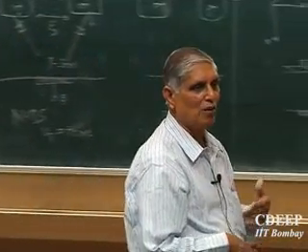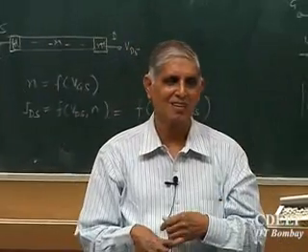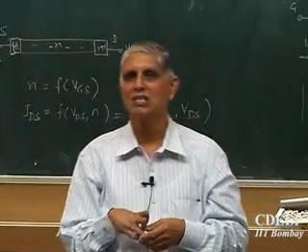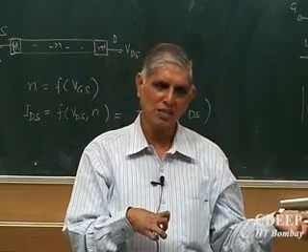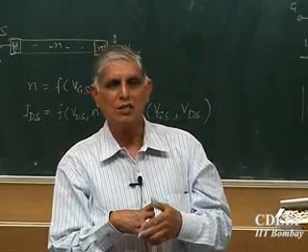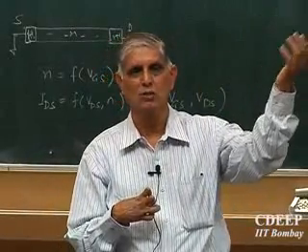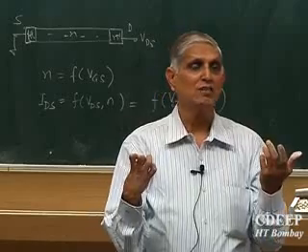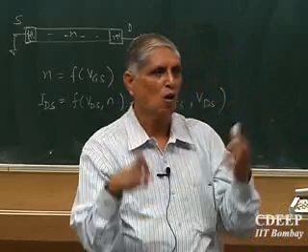We are trying to see, can we have, if not the same speed as BJT, then almost the same speed as BJT, even in MOSFET, but the additional advantage I should get is that power is extremely low. If I achieve that, then I say I have beaten BJTs. Because this statement should always be taken with a pinch of salt, but still one can say MOS circuits are much lower power consumption circuits than BJT circuits. Also we will say their speeds, if not higher, are at least now comparable with BJTs. MOSFET circuit speeds are as good as BJT speeds. Low power, and denser: for the same silicon area I can put a larger circuit in MOSFET than in BJT. Is that clear?